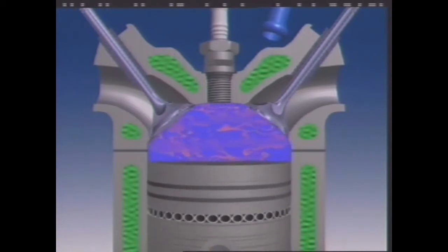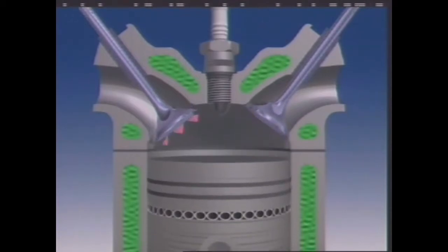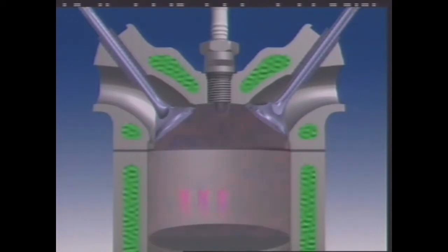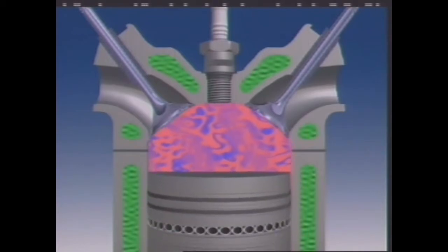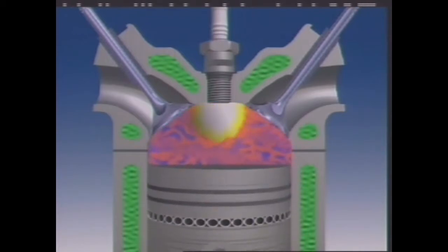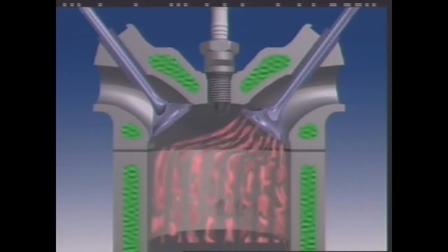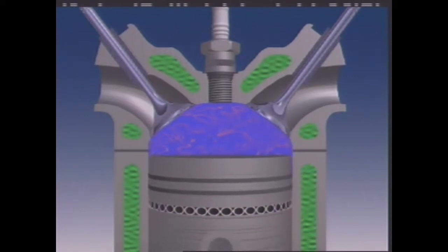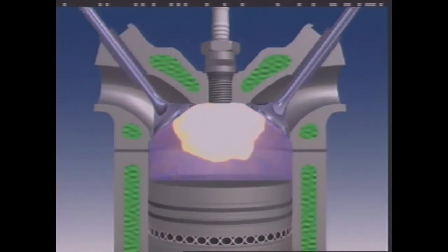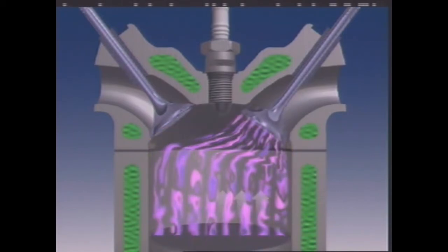Misfiring of the ignition can result in unburned fuel leaving the cylinder when the exhaust port opens. If an excessively rich air-fuel mixture is used, there is too much fuel for the quantity of air. Combustion will be incomplete, and any unburned fuel will leave the cylinder through the exhaust port. If an excessively lean mixture is used, then combustion takes longer, and the flame may extinguish before it is complete. When the exhaust port opens, unburned hydrocarbons will be exhausted from the cylinder.